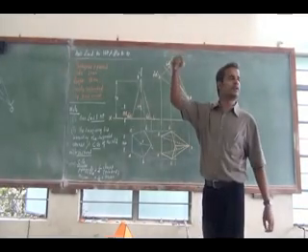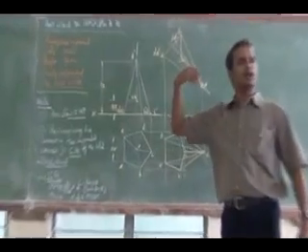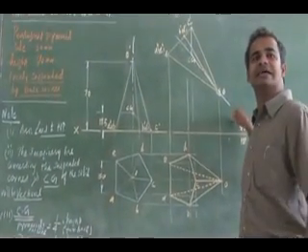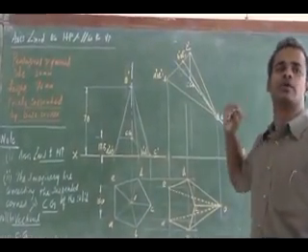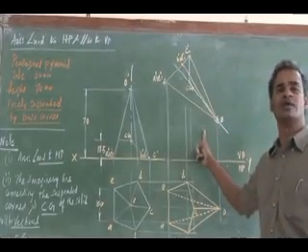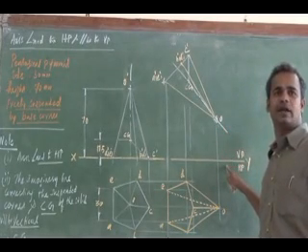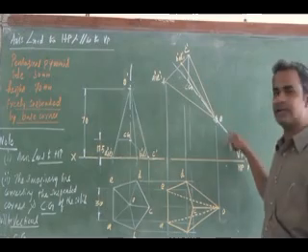It is suspended by the string such that the axis is parallel to VP and the apex is touching the ground. Apex touching the ground means this O has to exactly touch the reference line. How can I draw it? While drawing like this, it will be difficult.